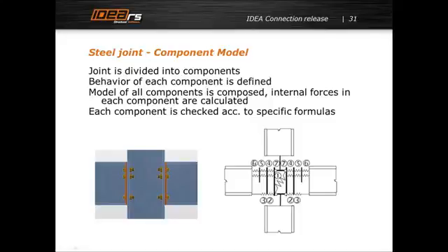And when you calculate this model, you get the forces in all these parts, like in bolts, in end plates, in flanges, etc. And for each of these forces, you can make the check according to Eurocode. Each component is checked according to special formulas which are described in books and in Eurocode.